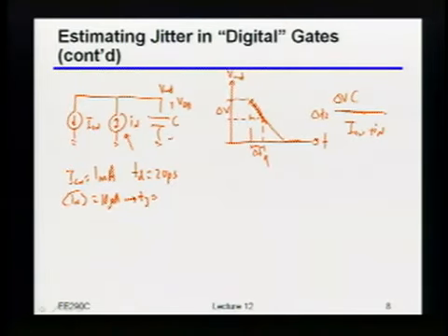Okay, so you're right, except that I'm just asking a slightly different question. But basically, you just normalize it, right? You basically say, okay, that 10 microamps relative to the 1 milliamp, that would be sort of my noise to signal ratio. And if I know what that noise to signal ratio is, I just multiply that by whatever the nominal delay was in the first place, right?